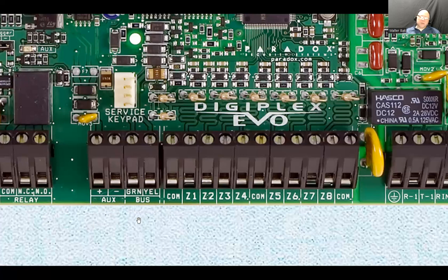Now here, remember we're talking about network topologies. This is the bus terminal, and it has only 2 wires. That gets connected to the bus terminal of any smart device. Usually it would be a keypad. This system is capable of handling many keypads at once. You could have one keypad in your lobby, another in your bedroom, another in your basement, another in some other doorway. Those communicate with this main board through a bus topology. There's just one pair of wires, terminated at the bus terminal of one device, and in a parallel way it keeps going, tapping in a bus configuration.